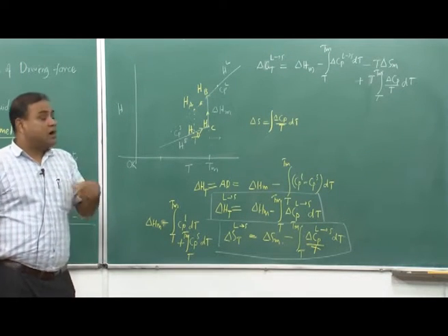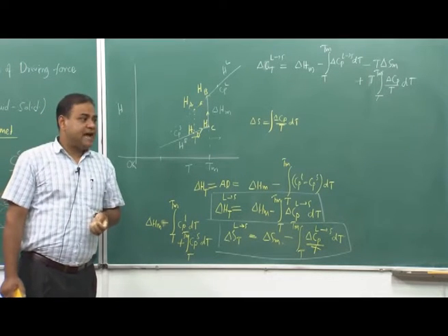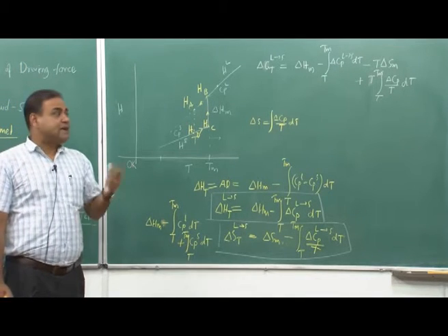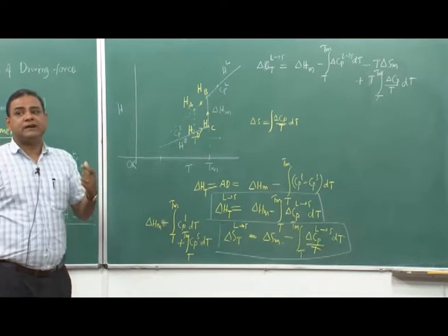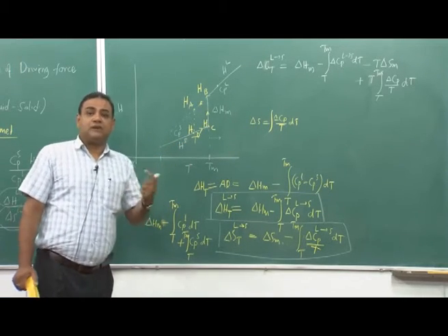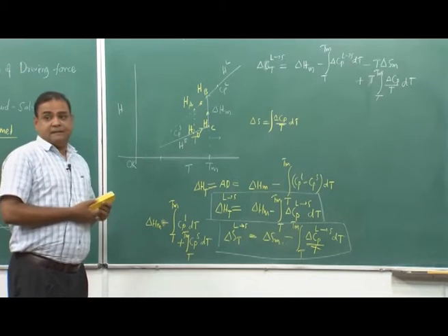That particular undercooling is possible if we can allow homogeneous nucleation in liquid. At that time we can maintain liquid as liquid below melting point, and we can easily find out the Cp. People do calculate Cp of liquid like that.